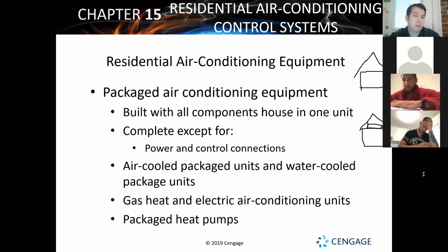Split systems are. Split systems are what you're going to see, I'd say 95% of the time residentially, where you've got the air handler with the evaporator and the blower motor on the inside, and then outside you've got your condenser along with your compressor.